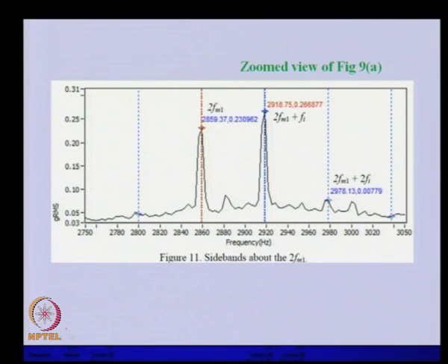This is another zoom view of the same figure. In this, you can see additionally we have two FM1, that is in the higher range we have shown here, and there is a sideband. So, the sideband is more predominant than the actual first tooth missing frequency. Here it has been modulated. Even this is the higher harmonic of the tooth missing frequency, the second harmonic of the tooth missing frequency, and the sideband of that. Here also there are higher sidebands, at twice the speed of the shaft.